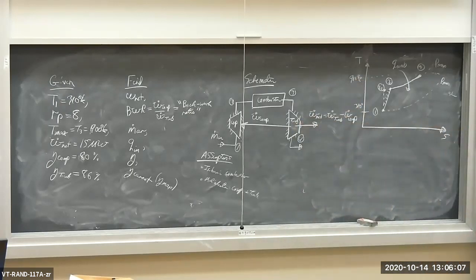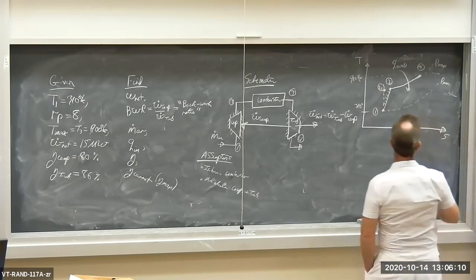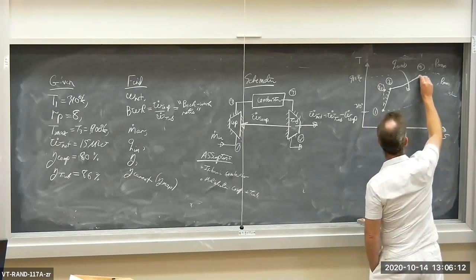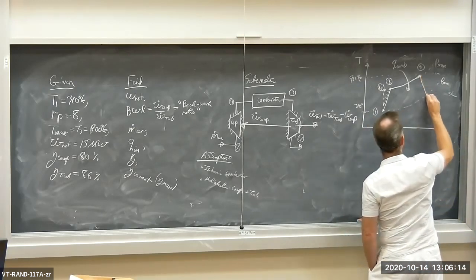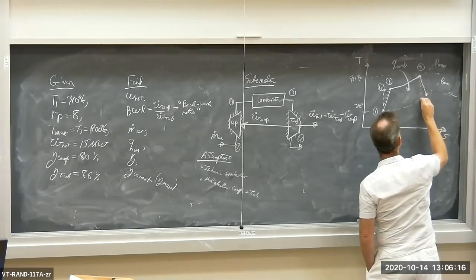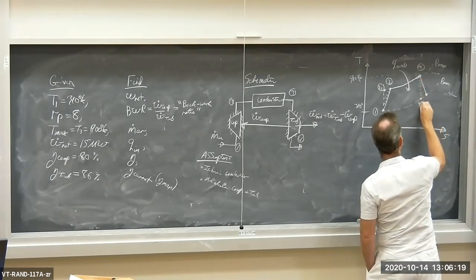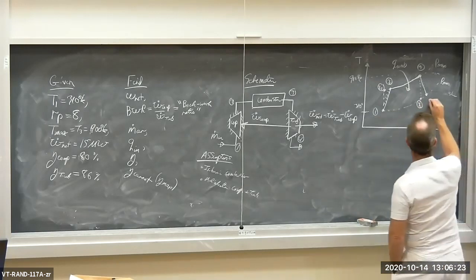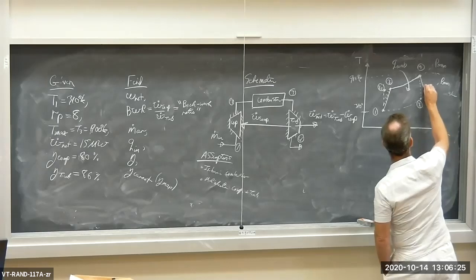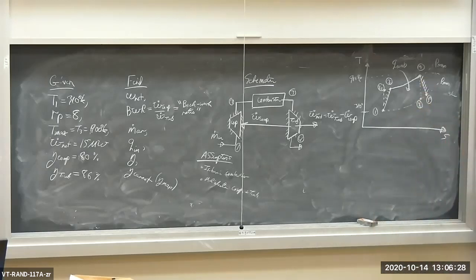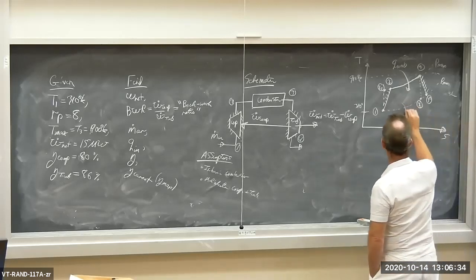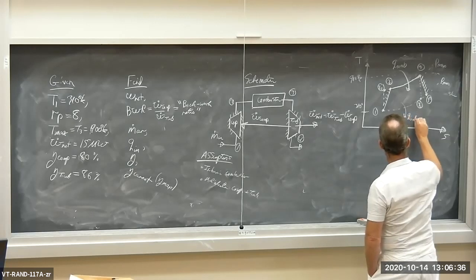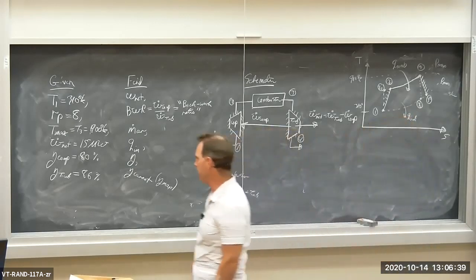Min and max temperature. And then we have expansion in the turbine. It's going to be irreversible, so there's going to be a delta S compared to the isentropic expansion process. So we expand from state 3 to state 4. There's a positive delta S because we have entropy generation, and therefore delta S is positive through the turbine. And then we have the heat rejection process going on in the environment, okay?